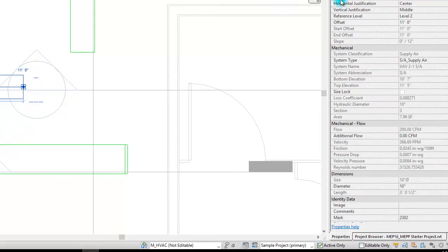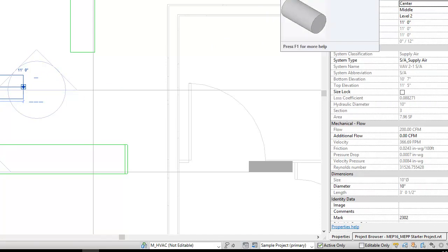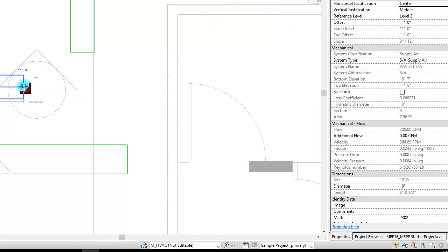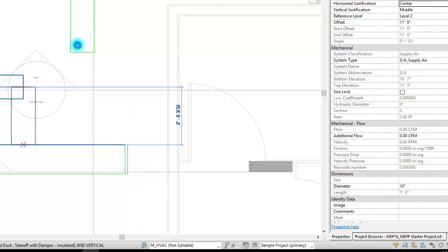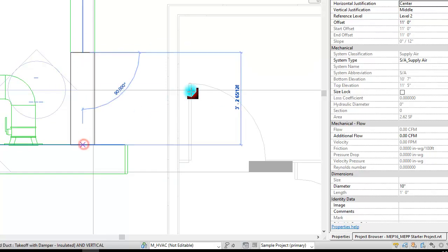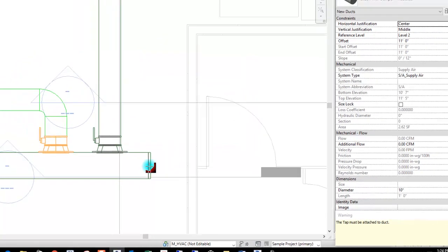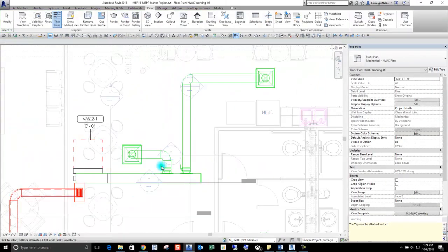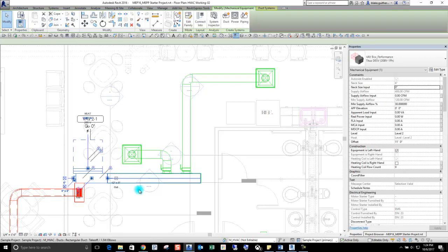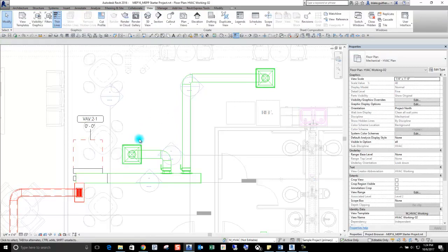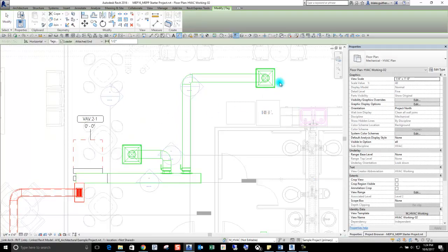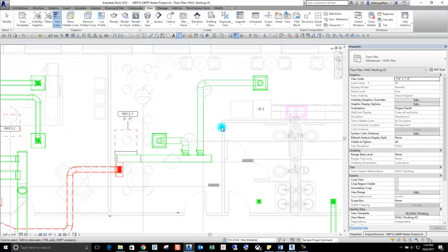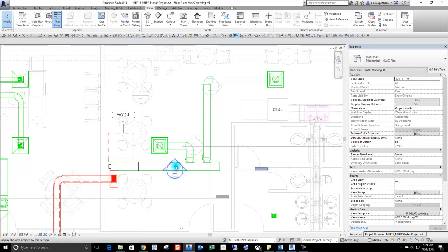And so now this was the branch settings that we used, round takeoff with damper on insulated duct. So let's draw that connection, and then we'll draw this connection as well. There we go. So everything's connected. Our VAV box now has 400 CFM connected, so both of these diffusers are at 200 CFM. So just like that, real quick to make your connections and modify your layout.